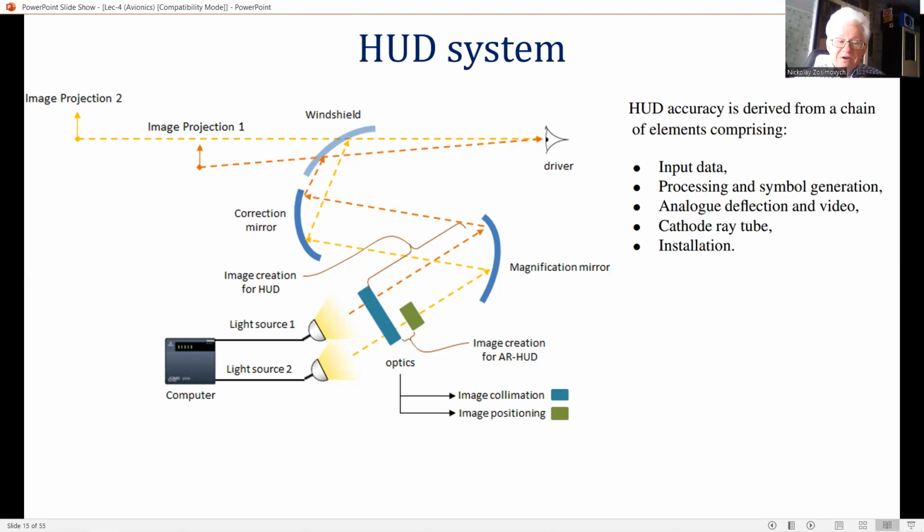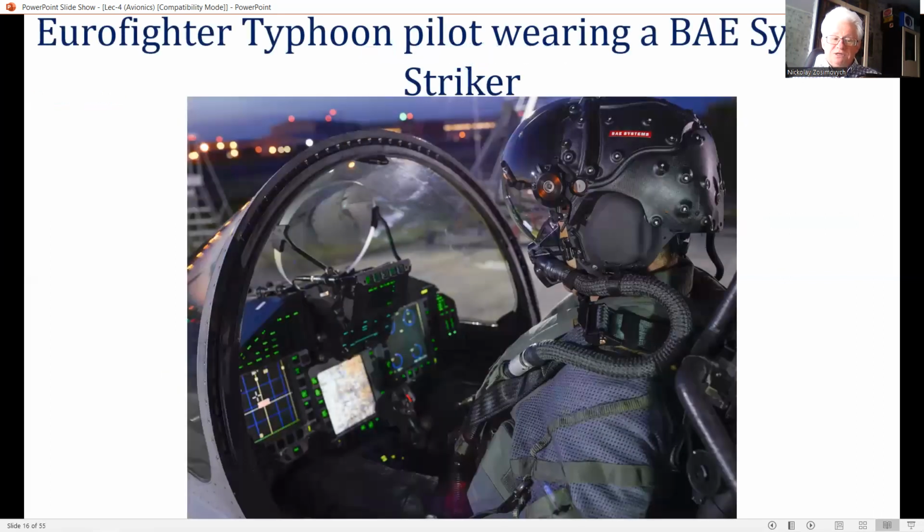Corrections can be readily applied in respect of windshield optical effect and symbol position distortion. Conversely, the HMD cannot be as rigidly located with respect to the pilot's eye because of limitations of helmet design, such as eye relief, weight, comfort, etc.